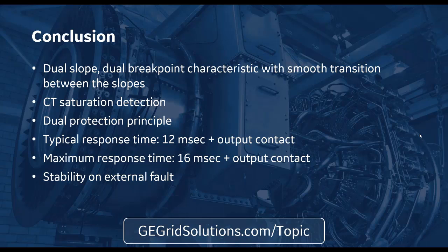However, in most of our relays, we've released an input card to deal with that issue, and it's called an active impedance card. One of the ways we typically design our circuit to deal with this issue is we put in auxiliary relays, right? You put lockout relays, auxiliary relays, because they require more energy to operate. So any type of capacitive discharge, any type of interference is not going to cause the auxiliary relay to operate. So basically what we've done is taken an auxiliary relay and put it into the microprocessor relay, so to speak. So we've put a low burden active impedance in the relay, and it's available in all UR relays, but you have to ask for it specifically for it to come with the relay. So if that's something that you're interested in, we can talk about that.